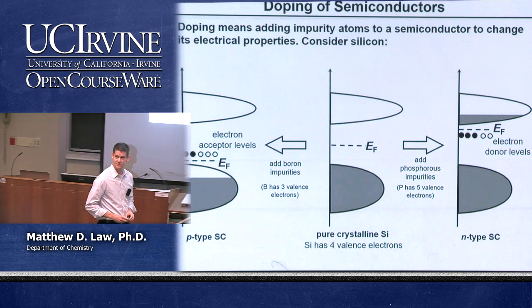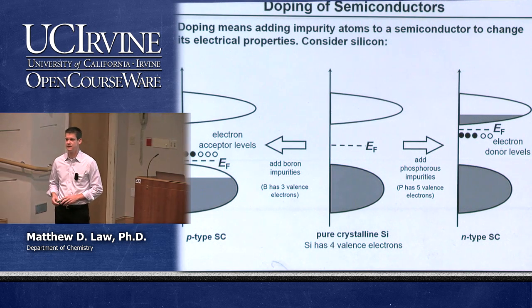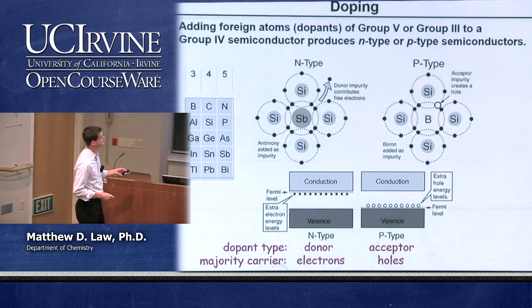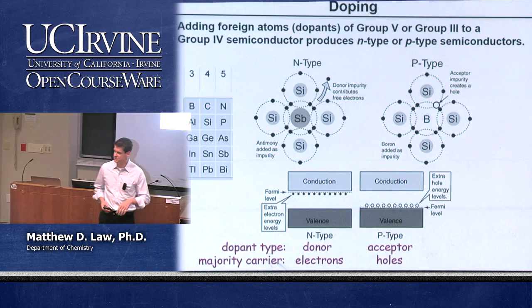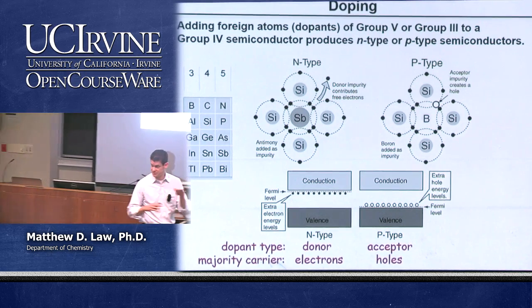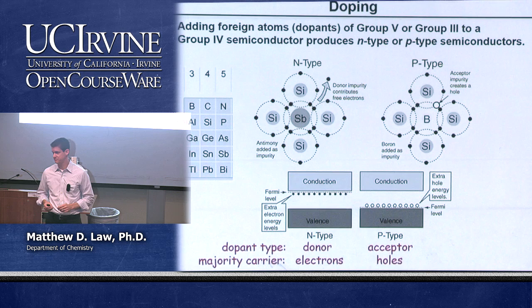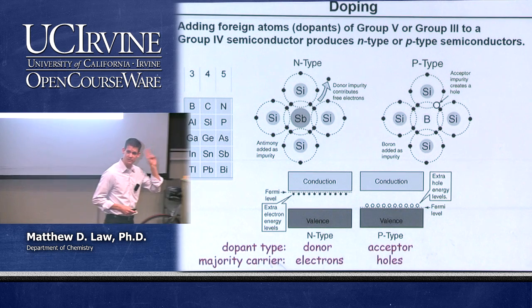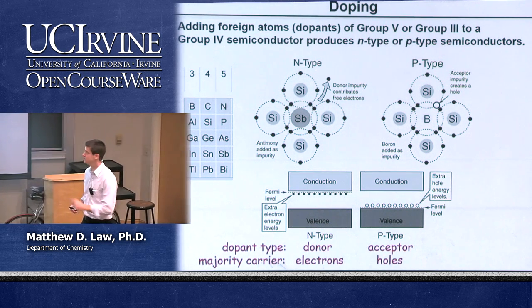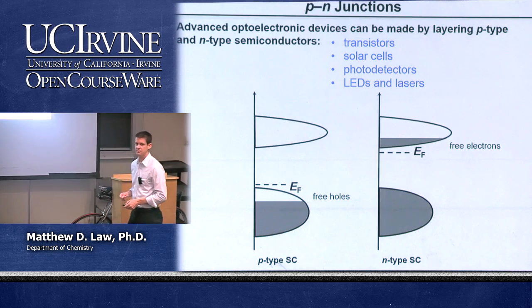Okay. Other questions? Yeah. In regards to this doping, is there an influence as to whether this is a metal, non-metal, or metalloid as well? It does, yeah. So what we've shown here is the simplest situation, an elemental semiconductor doped by a group 5 or group 3 element, just one valence electron different. The reality is a lot more complex if you start looking at other possible dopants. You can have dopants that introduce multiple states, states that are in the middle of the band gap. There are many different possibilities. And so we've shown just the very basic classical picture to understanding doping. Yeah, it's a very messy world out there, it turns out. But this is what Intel and other companies that make semiconductor devices are using. They add boron, they add phosphorus to their silicon. Okay? Other questions? Okay.